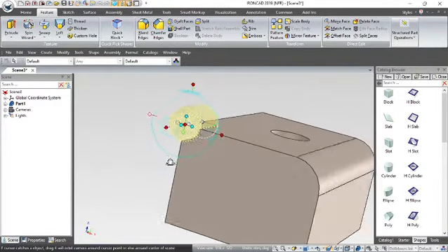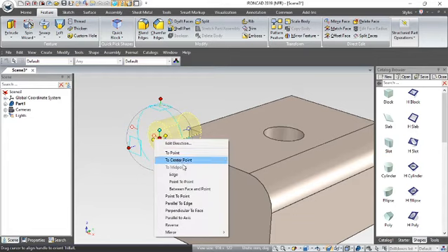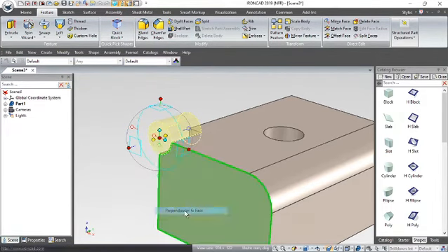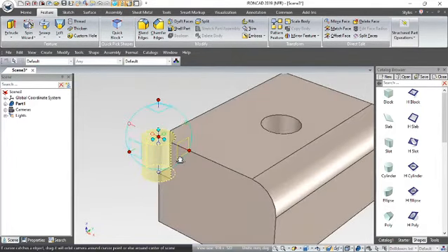And here we've got what I call a 3D compass, so you've got an inner sort of XYZ and an outer one with the handles here. So for now, if I want to rotate that down through 90 degrees, I can do it in two ways. I can pick maybe that handle there on that side of the tri-ball, press the right mouse button and go, let's do that. What we want is for that to be perpendicular to a face. So I pick that option from the drop down and just pick it there, and it's basically now in the orientation I want it to be.